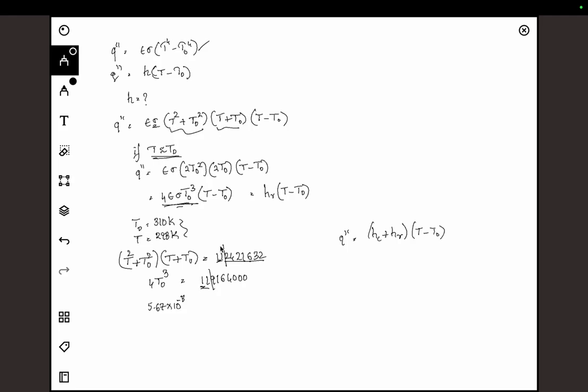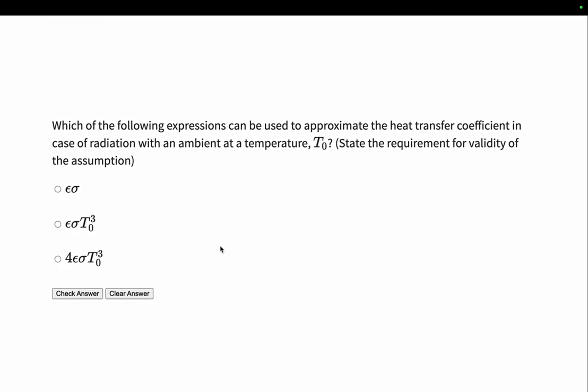In that particular case, you need to know what is the heat transfer happening on the outer surface of the window. There, you can approximate it with this HR because the temperatures there will be like 40, at max 50 Celsius, depending on the kind of coatings you have on the surface of the glass. So in those scenarios, you can directly assume these values of HR. The values will be provided in tables. So you don't have to solve the complete radiation equations, and this should be fine to calculate the net heat transfer on the outer surface of the glass pane. Is that clear?